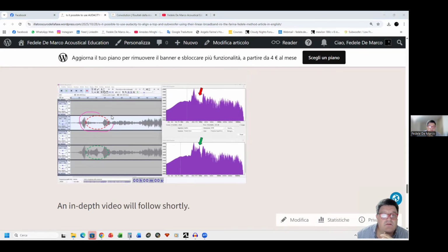Okay, here. And there is a dip also in the frequency response. You select all the channels and perform an analysis to show the spectrum. If I invert instead the polarity, I see the sum here in the waveform, in the recording of the waveform, and also in the spectrum.